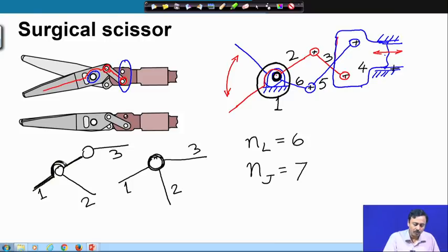So, this whole link is link 1. It is being connected to link 2 by this kinematic pair and to link 3 by this kinematic pair. This one is a special case of this, where this distance has gone to 0. So, kinematic pairs, remember, is always between 2 links. So, if 3 links are connected like this, you have to count them as 2 kinematic pairs.